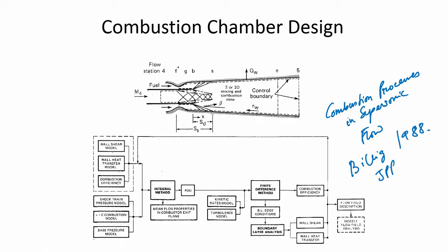What he says is that one can couple the integral method and the differential methods to develop a design. The integral method should give you the pressure distribution, but some of the integral method needs to be fed with the wall shear model, the wall friction model, the wall heat transfer model, the combustion efficiency model, the shock train model, and there can be a base pressure model. All these things should go into the integral methods.